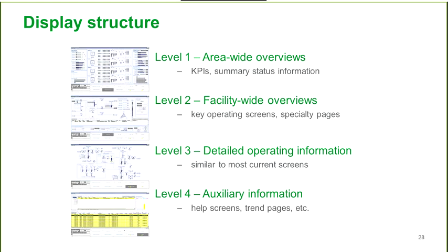If you go down one more level to level 3, then you get really down into detail. Now you're down to the P&ID charts. Here you have all your inputs and outputs. You can force your values on analog values, and also you can have a look at your PIDs.